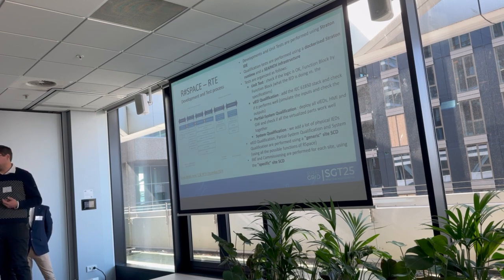Then we have a partial system qualification step. In this qualification step, we deploy all the virtual IEDs, the HMI, so the local SCADA we have, and the gateway, and we check if all these virtualized parts work well together. So if it communicates well and if it works well. And finally, system qualification, where we add the physical IEDs from our different vendors.